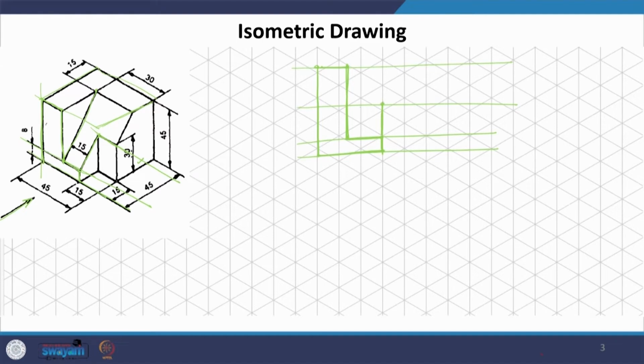There is no surface here, there is a horizontal edge here. In the back, there is no surface here, but we just have a line at the bottom level, and there is an edge which is joining this, and then there is another edge which is joining this level and this level, which is this, and at the top we see another edge, right. So, this is what we would see in the front elevation when seen from this side.